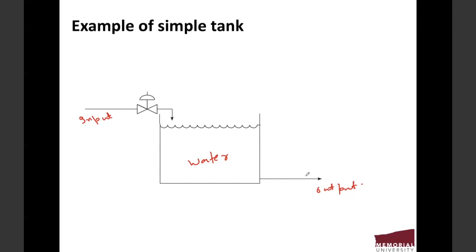In order to control or maintain the water flow into this tank, we use some instrumentation and process control. And these are those control systems. This LT is your level transmitter. This is the pneumatic transmission. Those of you who have an electrical or chemical background might be able to understand it well. And this is my level controller, this is my input and output, and these are my electrical signals.